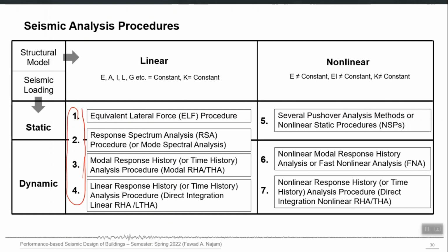You will be providing the reinforcement and cross section size corresponding only to 100 kilonewton, as though the applied action is 100 kilonewton only, right. And that cross section and reinforcement will be sufficient for that action which was otherwise capable of producing 800 kilonewton force, right. But that was if the structure were linear elastic, right.